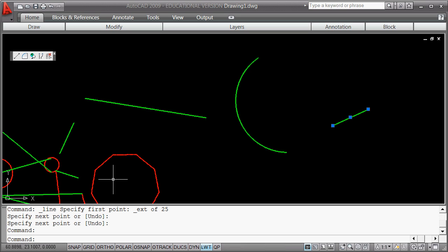do. Very often you might want to start by doing this visually and actually doing the drafting, and then go ahead and cutting it up, going back to where you were. So in fact, in this case, you could have extended that arc to a 25 and then drawn the line and then cut it back, but that's not necessarily that efficient when you get into other things. So let me keep going here.